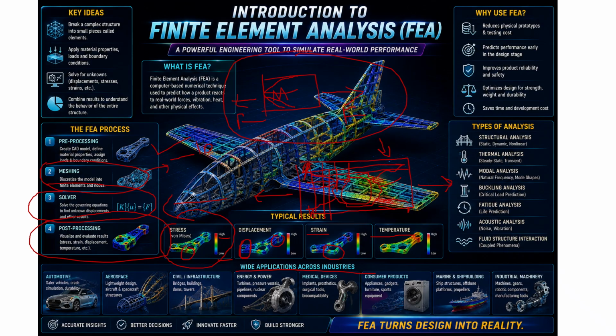Then we have to interpret how these stresses are going to be there and how the part will behave. Sometimes we give the wrong boundary condition and wrong stresses are generated at the wrong end. So we have to be very careful at the start of the FEA, in the pre-processing. If you made a mistake in the pre-processing, your entire analysis is going to be wrong.